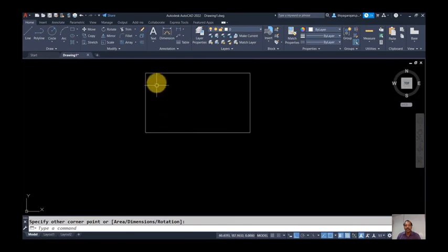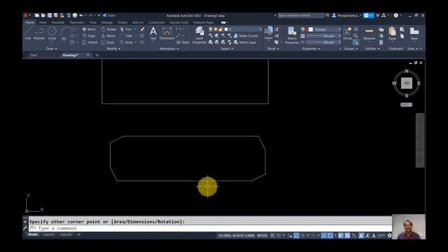You see here, the corners of the rectangle are very sharp, that means 90 degrees sharp. I want to chamfer them or make a curvature. So what I can do is, in the rectangle command, choose the chamfer option. Chamfer means flat at the corners. You need to specify 2 chamfer distances. Let me go for first chamfer 10, second chamfer 5. Then give the first corner and the second corner. See here, this is our first line. Here the first chamfer distance is 10, and here the second chamfer distance is 5. After this, this is the second line. So from here, this is 10 mm, 5 mm.